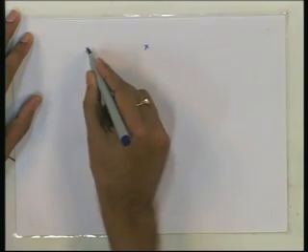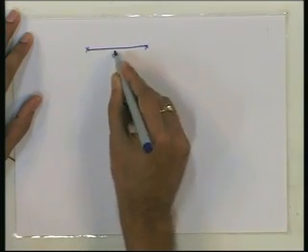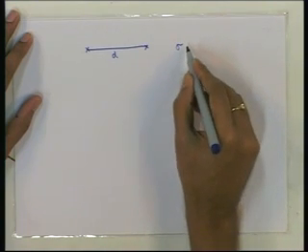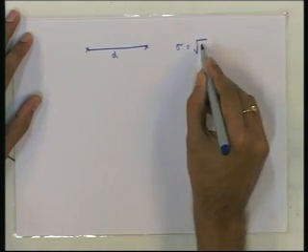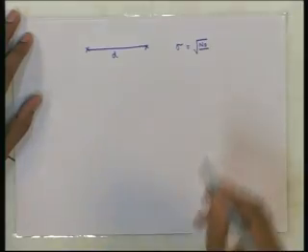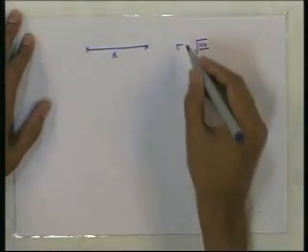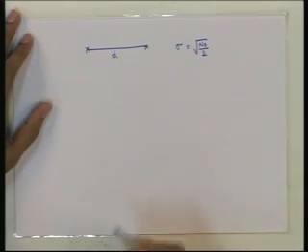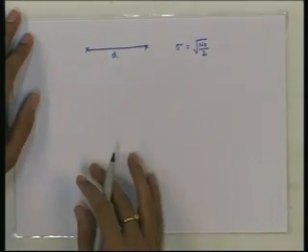So, in the last class we saw that for a binary signal set, if we have 2 points at distance d from each other, and the noise standard deviation sigma is nothing but root over N naught by 2, because sigma is the standard deviation of the noise component per dimension.